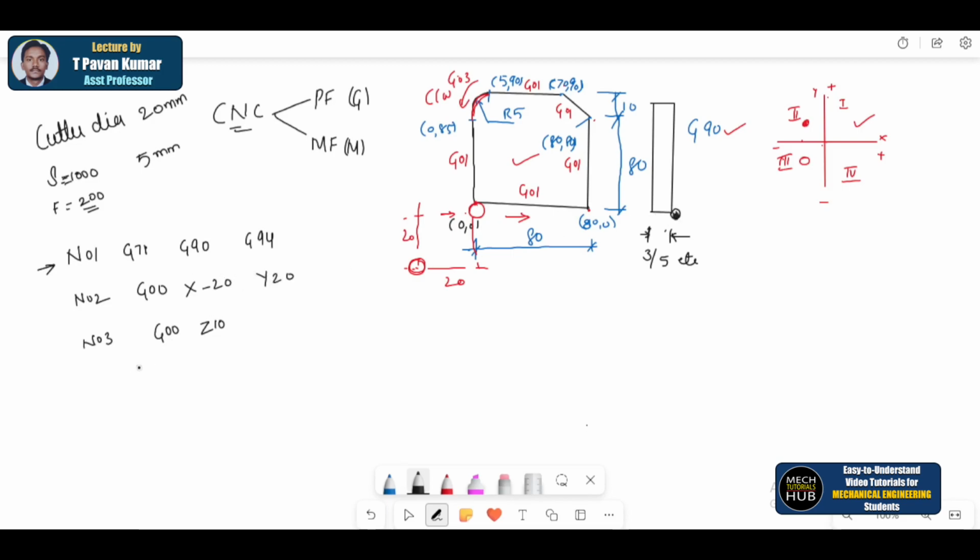It is almost at the tip of this particular thickness. Imagine that way. If that is the case, next I can say N4 followed by G01, linear interpolation. The tool has to travel all the way. Before that it needs to be compensated. Then the Z value should be given negative. Then whatever the speed given, write it down. Feed given. Then followed by, start the spindle.